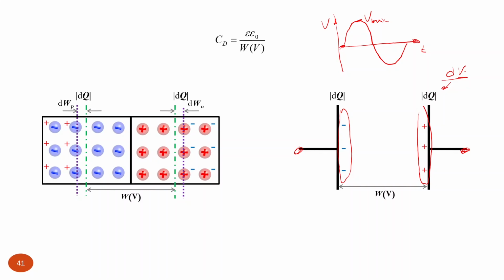When we apply some AC voltage, we need to understand how we get these charges. So also, some small change in potential difference of the AC signal will result in a small change of electric charges. But the important thing is where they come from. We can change electric charges in the depletion region only by changing its width.